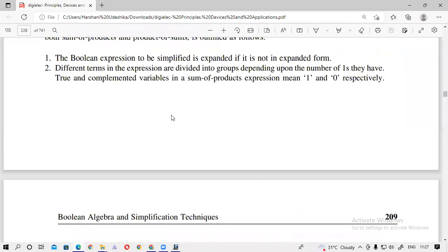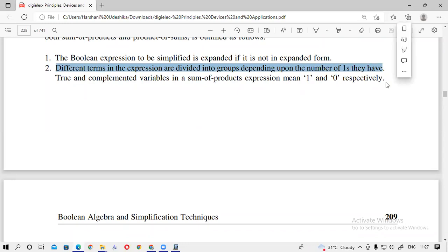There is a little difference when we apply this McCluskey method when dealing with product of sum and sum of product. Actually that is the difference. If you have drawn the K maps for sum of product, you already know this.